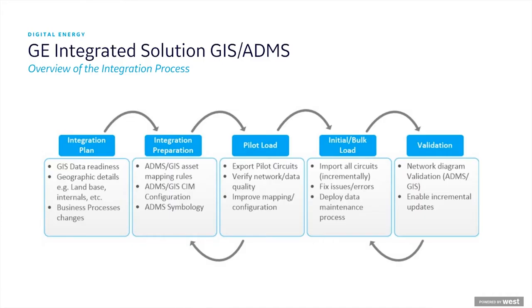So we've been through the piloting and loading of things, and we're now in production. We've imported all the circuits. Like I say, I finished importing them all yesterday afternoon. We've validated them at a visual state. So every connection, every transformer, every switch has had eyes laid on it to see whether it is electrically sensible. Certainly some of the GIS data in there that we'd drawn was not drawn in an electrically likely manner. We've connected the fuses on the wrong side of things.